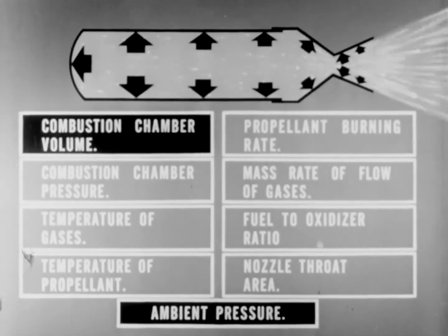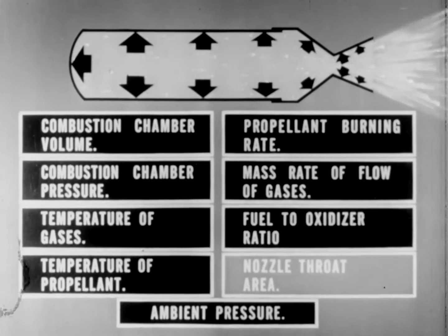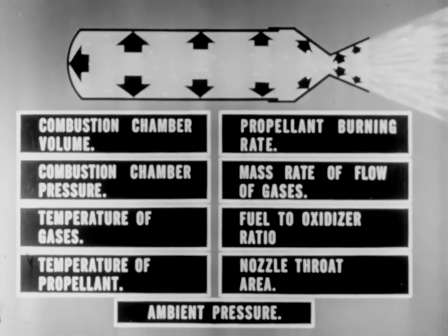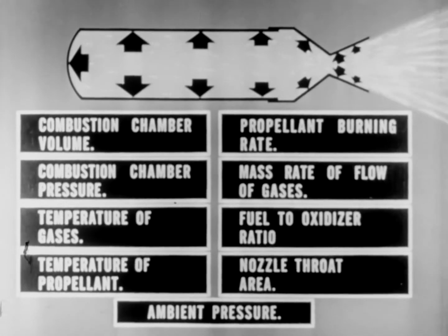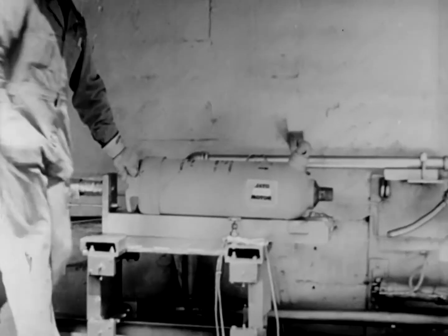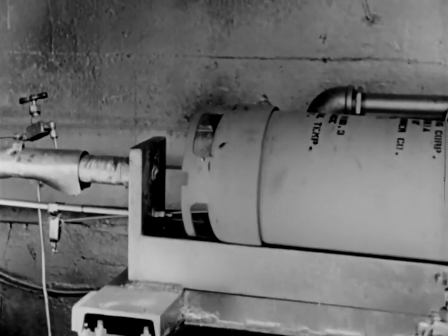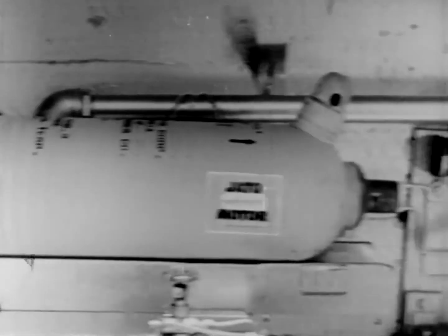An efficient rocket motor design must bring all of these factors into correct mathematical balance. This is true whether the motor be of solid or liquid propellant type. Let's consider a solid motor first. Like all rocket motors, it has a combustion chamber and a de Laval type nozzle.